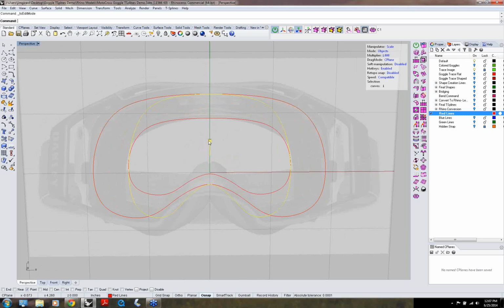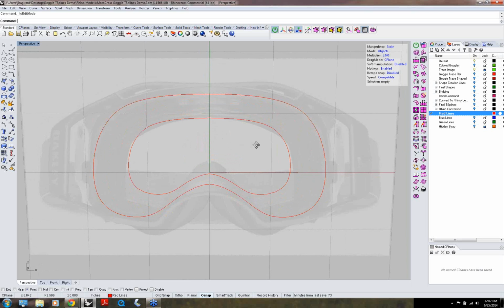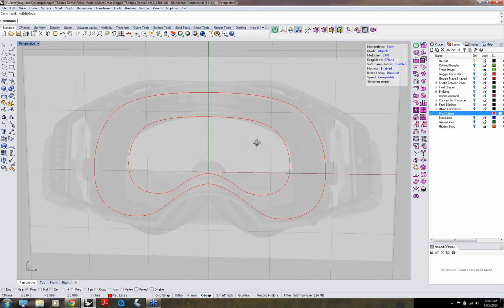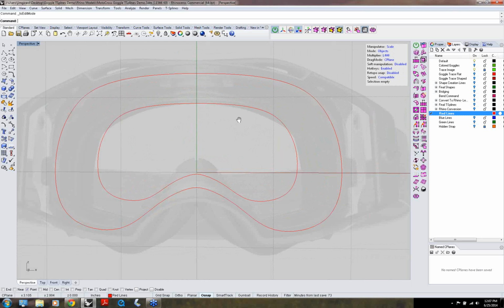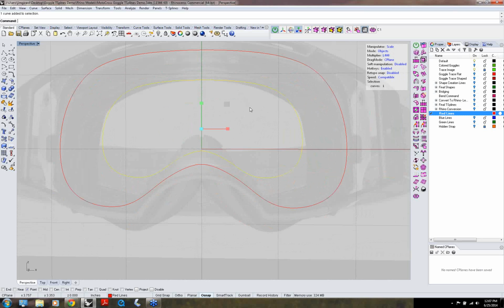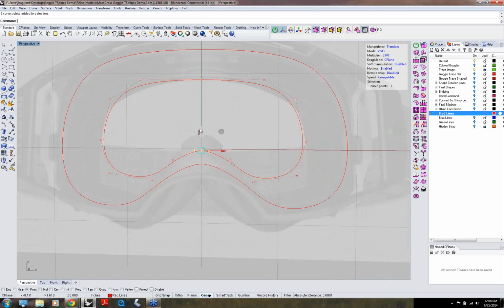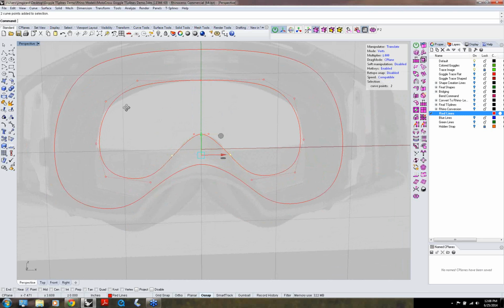And the reason I do this is I want to maintain the same number of points. I'm very cautious and careful about how I maintain the points, because when you create your surfaces, then they all flow together. So sort of groundwork and planning does go a long way in both Rhino and T-Splines, as many of you know. So as I come over onto the second one I made, I can turn on its points, and then again, using T-Splines, I can just pull them up to where I want them. And so it's a wonderful tool.